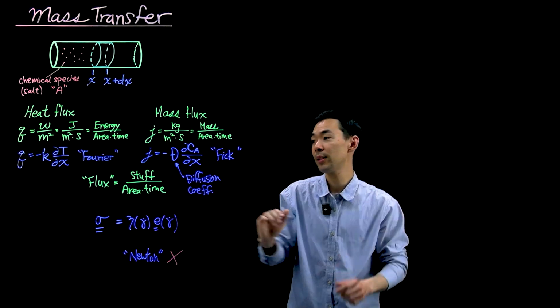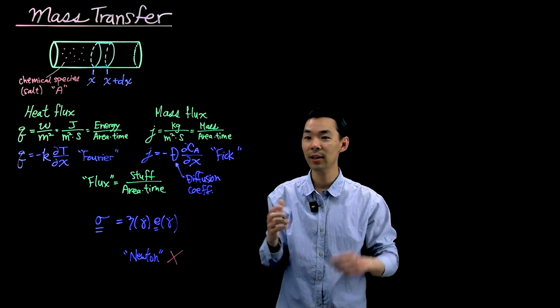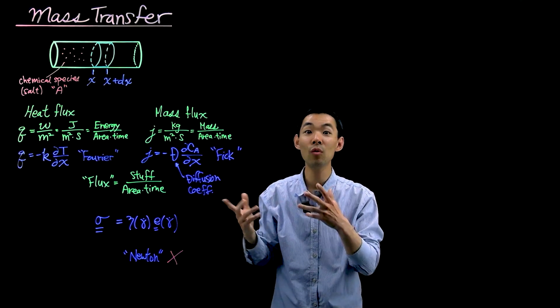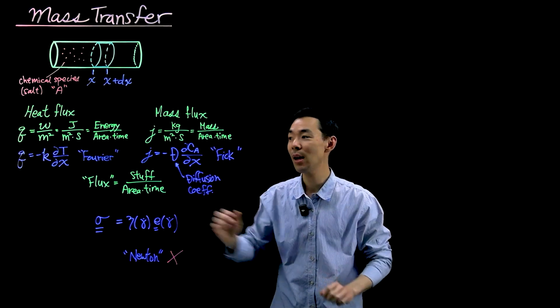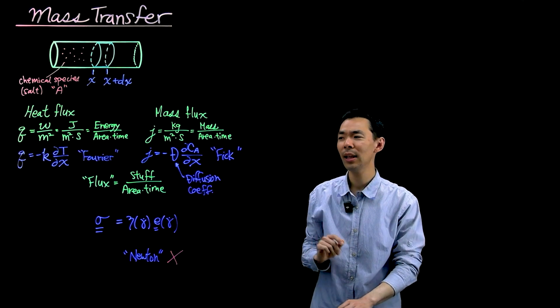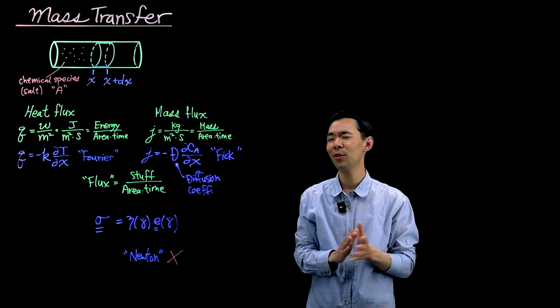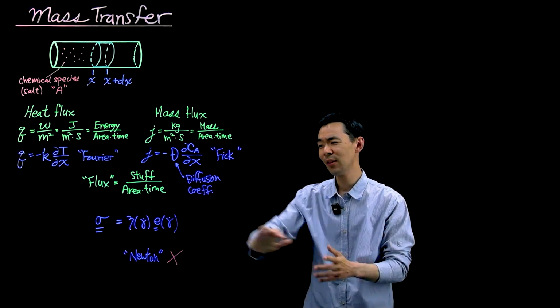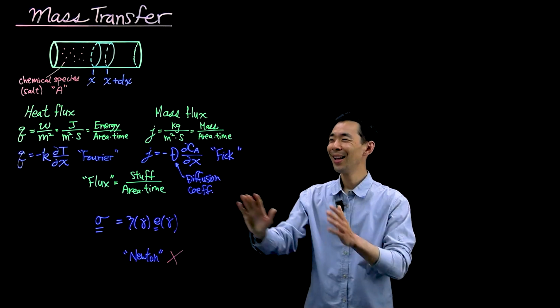It would be analogous to having the right-hand side here not just be proportional to partial T, partial x, but quadratics or cube roots of that, or T squared. Very highly nonlinear, complicated couplings of temperature and its gradient. And that's why fluid mechanics is hard for a million different reasons. There are other reasons too, but this is the entire field of what's called complex fluids and rheology. Okay, that was an aside.